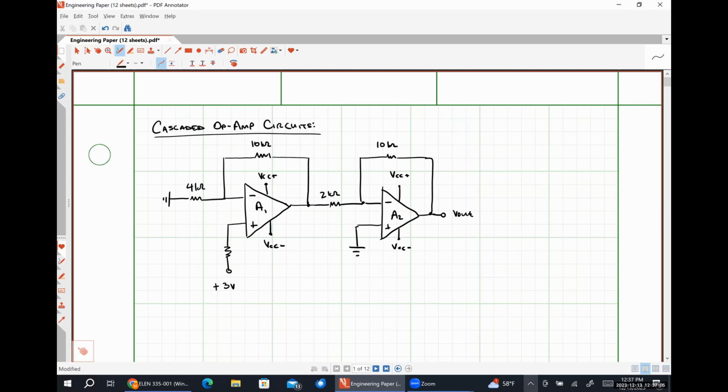So we are going to analyze this circuit. I'm going to call it the hard way first, but it's not particularly difficult. And then we're going to go back around and talk about looking at it from a different perspective here. Okay. So the hard way is going to be effectively applying the rules that we've used previously to analyze negative feedback op-amp circuits. So I can observe from the jump here that this current is 0 amps. This current is 0 amps. I forgot to give this resistor a value, so let's call it 1 kilo ohms. This current is 0 amps. This current is 0 amps.